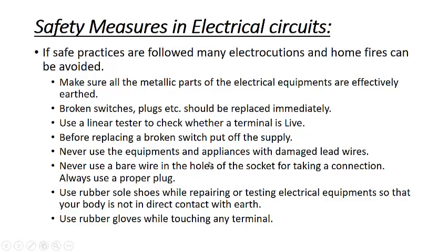Damaged wires may result in electric shock if somebody touches them, and if another wire comes in contact with these damaged wires, it may result in electric shock or a short circuit. Never use a bare wire in the holes of a socket for taking a connection. Always use a proper plug. You should avoid such practices. Use rubber sole shoes while repairing or testing electrical equipment so that your body is not in direct contact with earth.